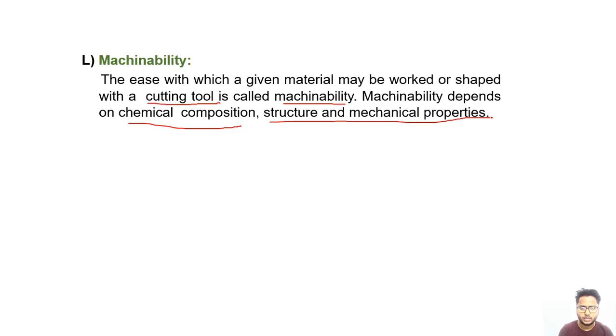If the material is very hard, then it is not machinable. If the material is very tough, then it also does not have machinability, because for the material to be machinable it must fracture due to the cutting tool. If the material is very tough, it will not fracture, so it will not have machinability.